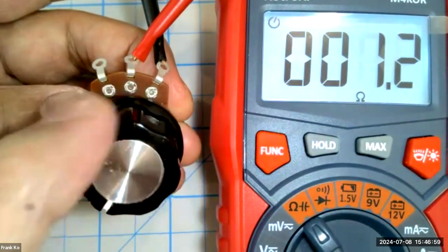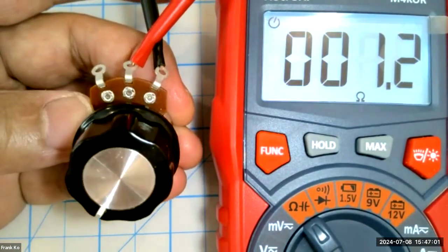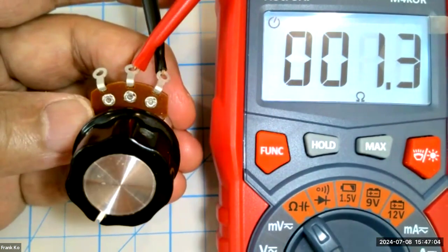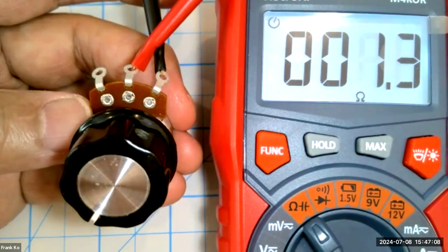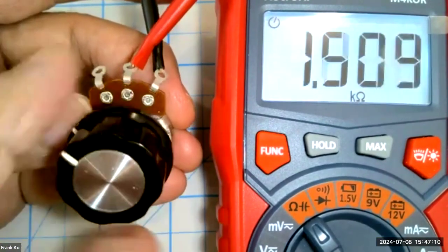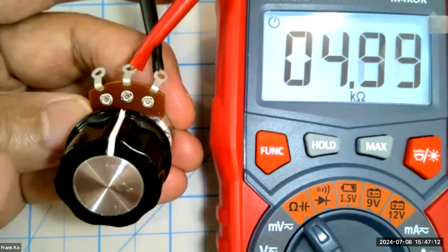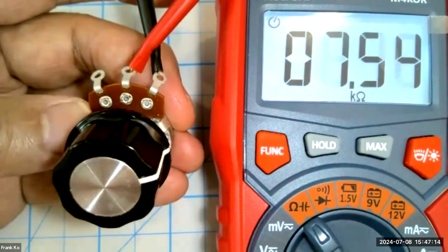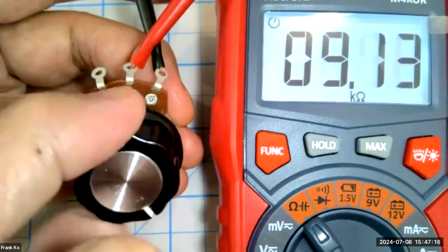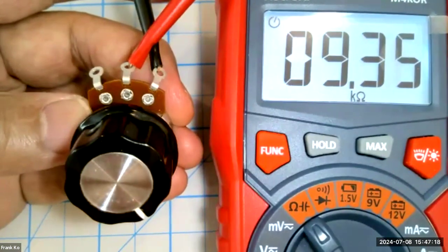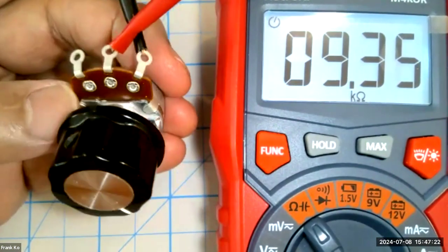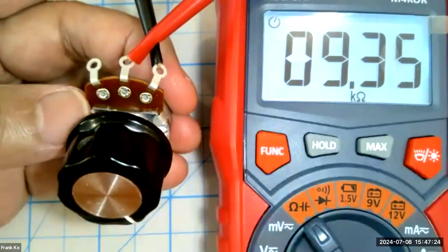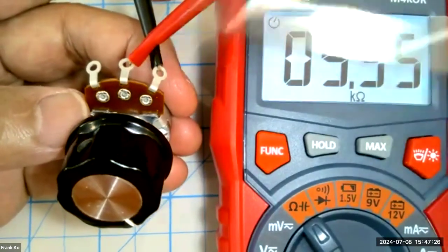So as we rotate traditionally to the left, we would expect a lowering of volume, lowering of brightness, in this case, lowering of resistance. And if we rotate clockwise, we can see that increase gradually, increase more as the knob continues all the way over to the other extreme. Voila. So this is how your potentiometer works on the outside pins and from one middle pin to one of the outside pins.